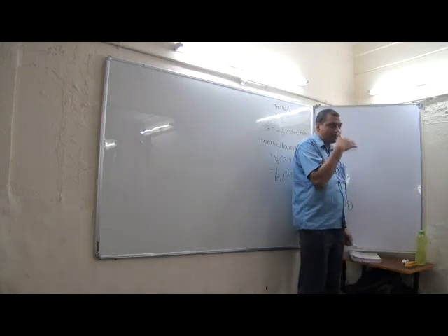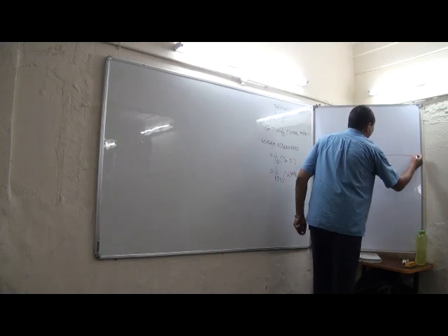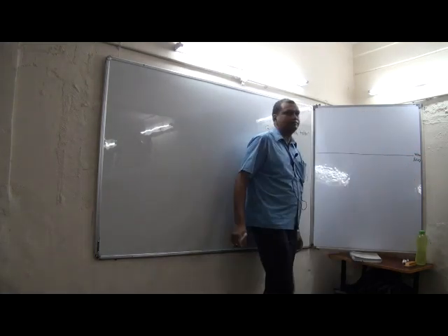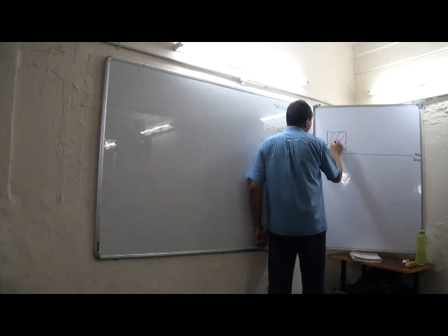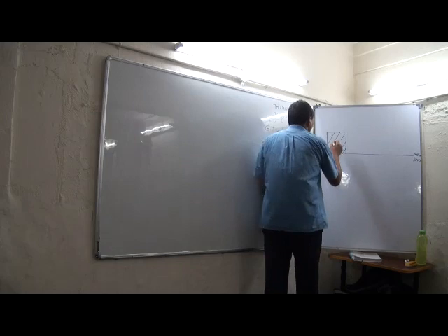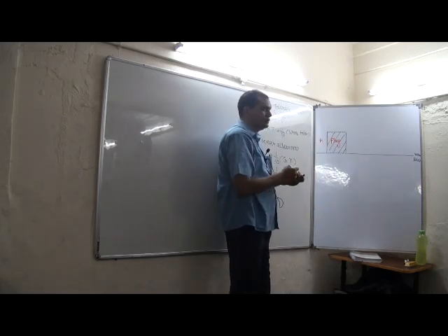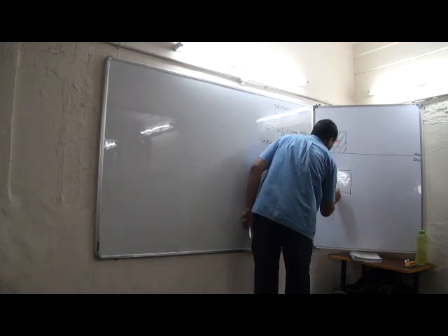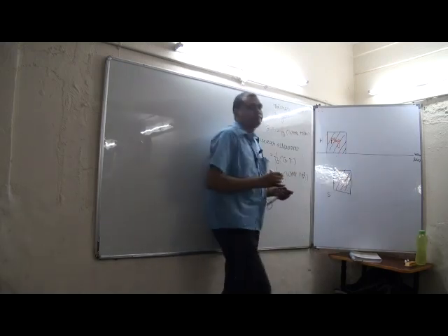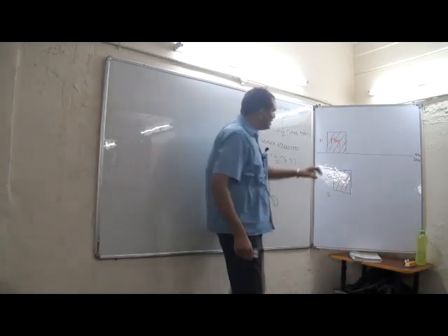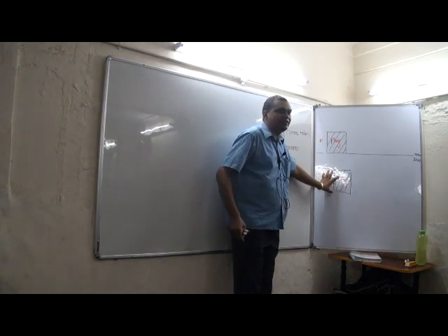Now the question comes, we have to provide the tolerances. So once again, everybody look at the board. Let us say this is our zero line, and let us say this is the full tolerance. The plug gauges will be designed here. This is the hole. And let us say this is the shaft. So the ring gauges will be designed here. For the plug gauges, this is the work tolerance, and for the ring gauges, this is the work tolerance.